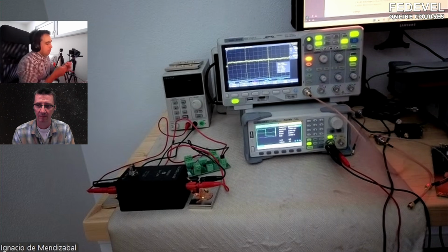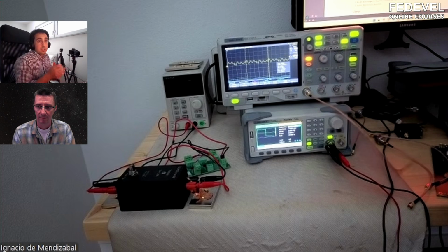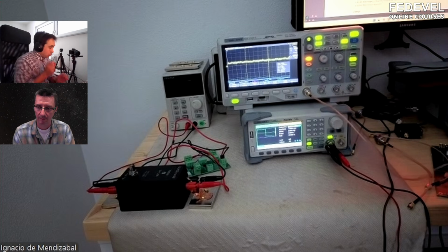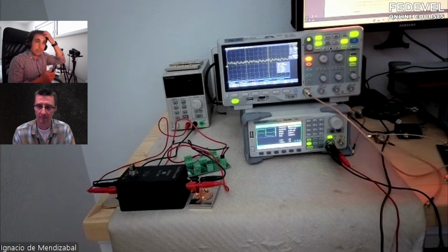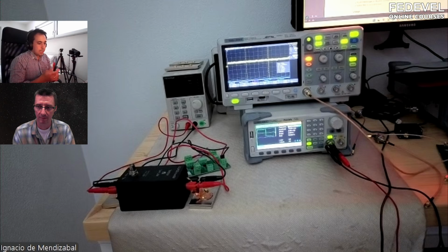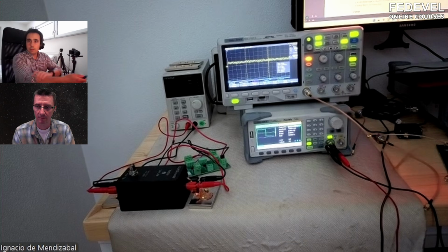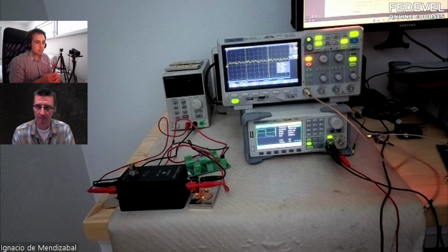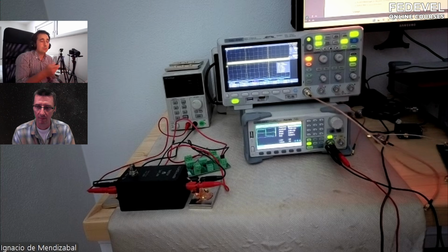And so the main difference, and what I like, is the mechanics. It has a plastic handle, and by the way, one thing you need to be careful about when you use near field probes is that they are not isolated. So it can be dangerous to use them directly with high voltage, higher than 60 volts, voltage levels that can be dangerous for us. So always be careful when touching and when moving close to high voltage.